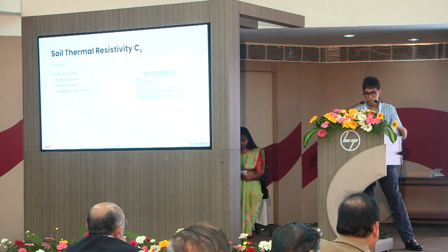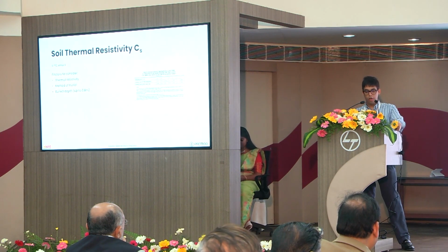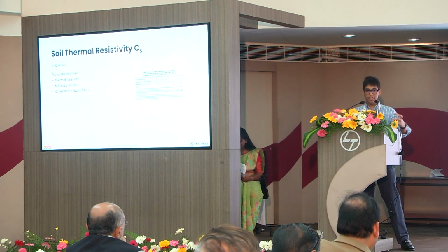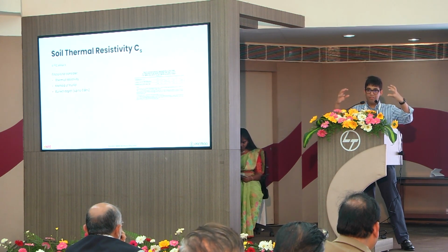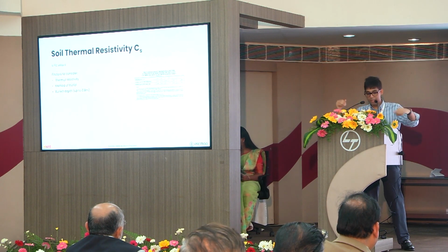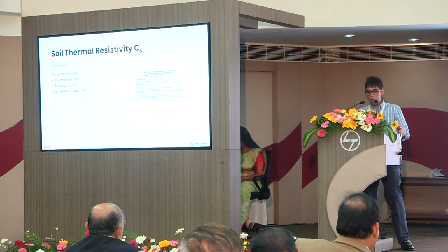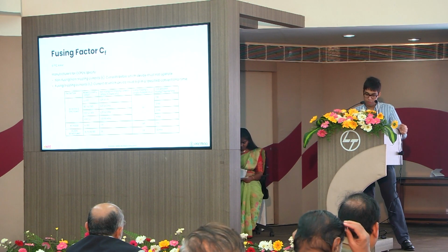So this is quite important, because if we do a soil thermal resistivity study, usually these are given by area. Basically, soil thermal resistivity is the ability of the soil to dissipate heat. If the soil has very high thermal resistance, the cable will be able to dissipate heat into the environment slower, hence the cable has to be derated. And also, the deeper you go, these change. So this table only covers buried depths up to 0.8. IEC 60287 goes further into this.